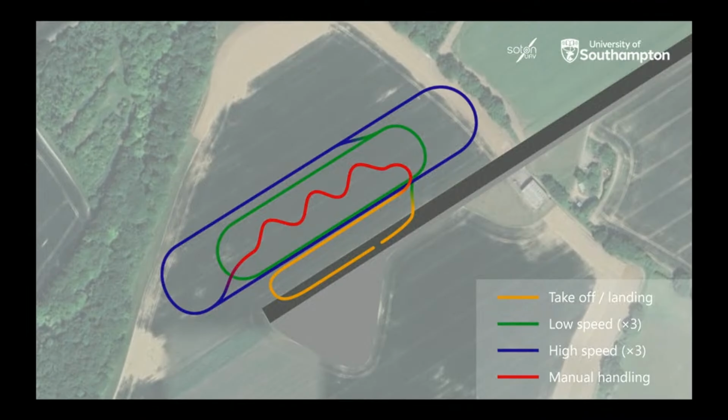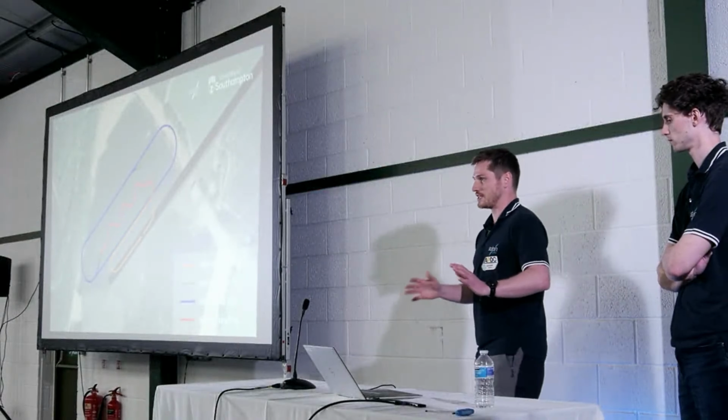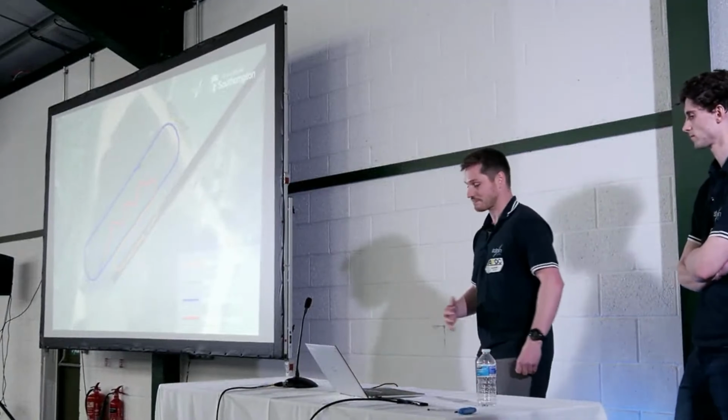After that, we switch to a high-speed circuit, and this is where it becomes slightly semi-automated, and that's because we use the throttle nudge feature to bring the throttle up to 100%, and we've cleared up the high lift devices. And again, we try to do 3 high-speed circuits. Again, we might not manage 3 because their design might be really draggy, or the high lift devices might not have fully retracted, and therefore we've got this heavily draggy system.